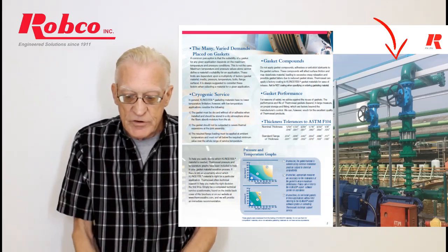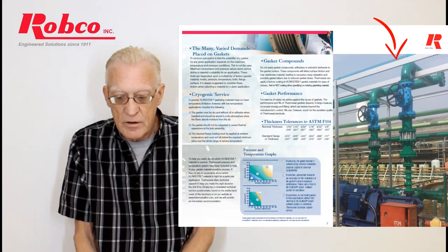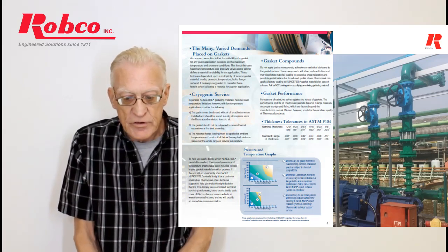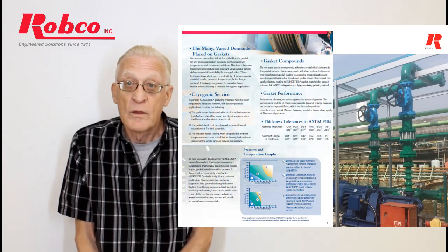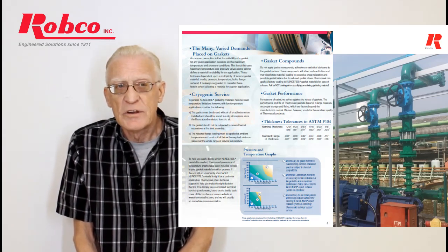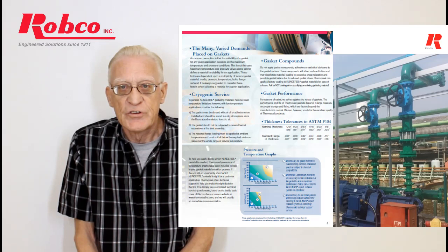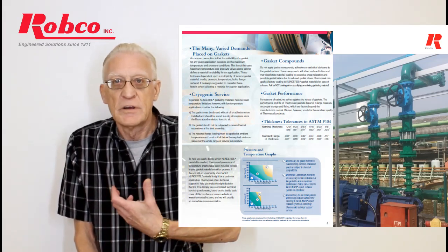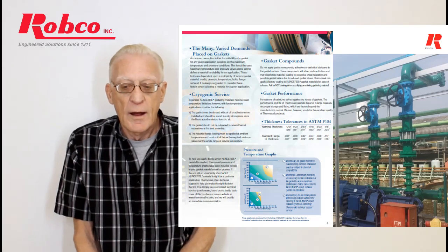On the right-hand side, you see all the flanges and the piping and the valves that are put in and so on. Gasket compounds, for example, are a no-no. Back in the old days, the asbestos gaskets would stick incredibly after 2 years in a steam line or whatever.